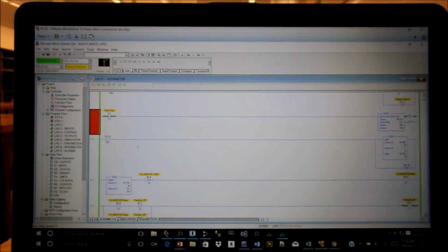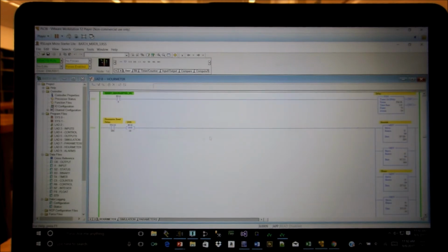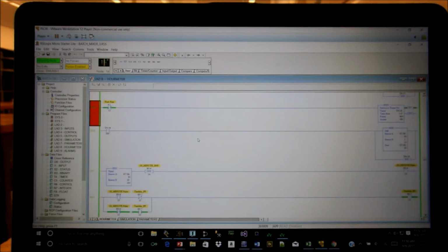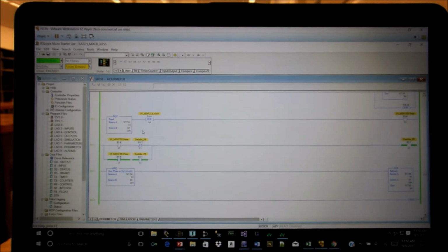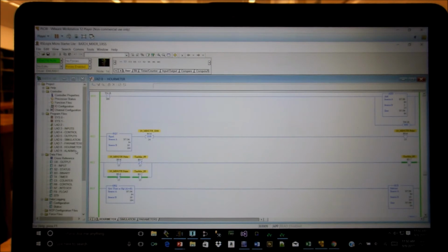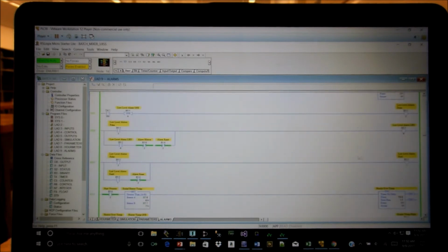And then we have some hour meter functions that are basically for our runtime. And this has the runtime of the system. And then we also have something down here which is just a 10-minute strobe, so we're clocking data in at 10-minute intervals. That's another feature that we added to the program from the original LogixPro. And then we've also added some alarm systems to our alarms.